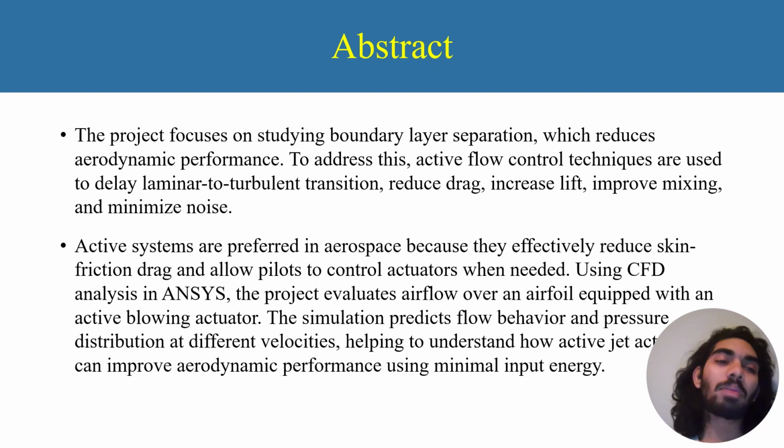Firstly, the abstract. My project primarily focuses on studying boundary layer separation. Boundary layer separation is a process where, if the angle of attack of the airfoil, the wing of an aircraft, increases beyond a certain point, the lift-to-drag ratio is going to reduce, which may cause the boundary layer separation. This separation reduces aerodynamic performance.